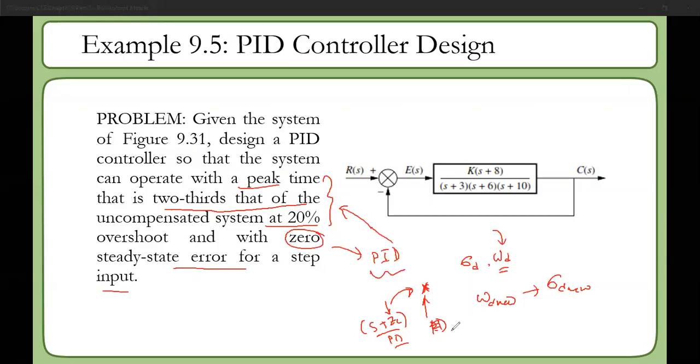If you're happy with the values, then we go for the calculation of your PI controller. It depends on how much you want the pole at the origin and how close you want to make it. So it depends on you. You can make it 0.5 or 0.01 or 0.1. Based on that, your previous values of your PD controller will be more or less closer to that.